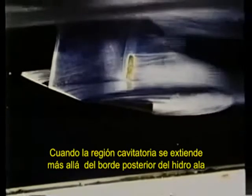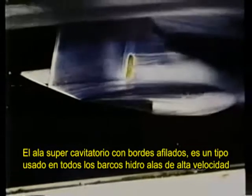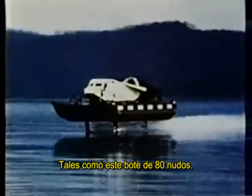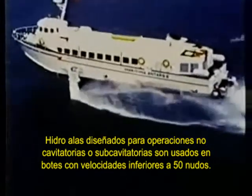We are lowering the pressure by dropping the water level above the foil by means of an upstream sluice gate. The cavity also grows when the water speed is increased. When the cavitating region extends beyond the trailing edge of the hydrofoil, we call the flow supercavitating. Sharp-edged foil is a type used on very high-speed hydrofoil boats, such as this 80-knot boat. Hydrofoils designed for non-cavitating or subcavitating operation are used on hydrofoil boats at speeds below about 50 knots.